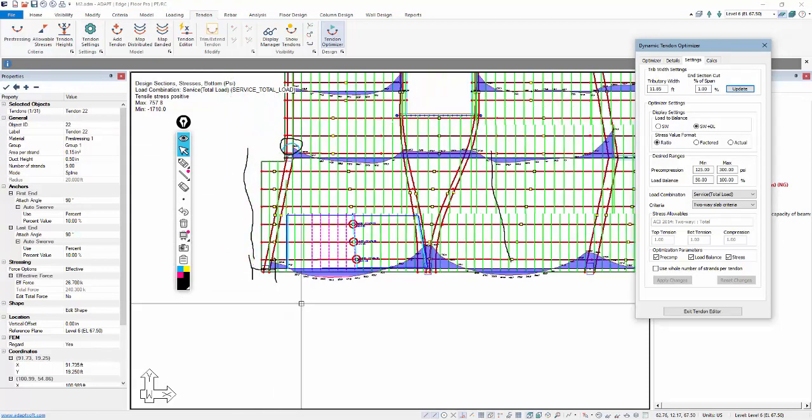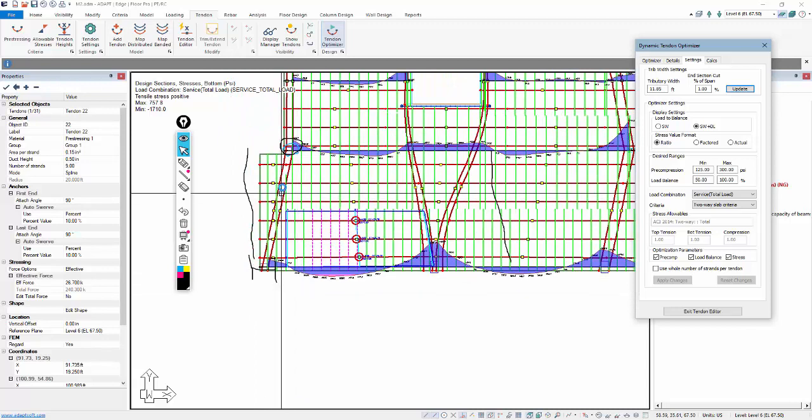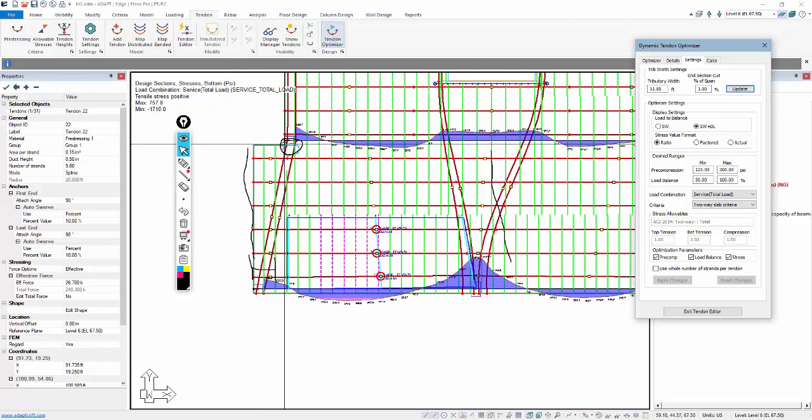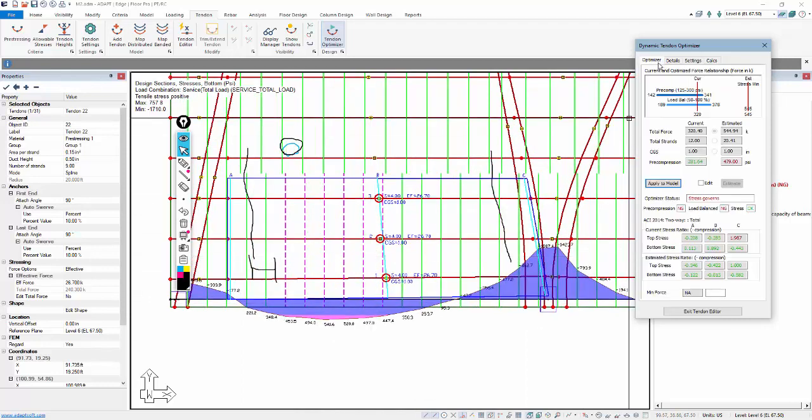And what's likely happening is it may be being referenced off of that corner of the slab. So that's something that we'll have to check. Obviously there's not an overstress here, so it's not as critical, but you want this cut to be as close to that face as possible so that you can compare it with the cut and the values that are calculated per the finite element results versus this optimization result from this actual algorithm. And so let's go ahead and take a look at some of the values.